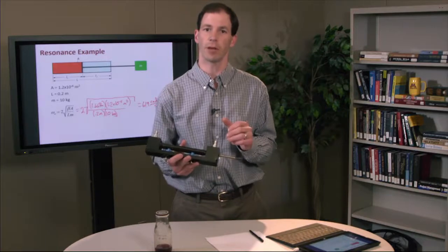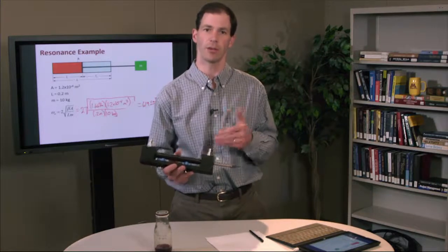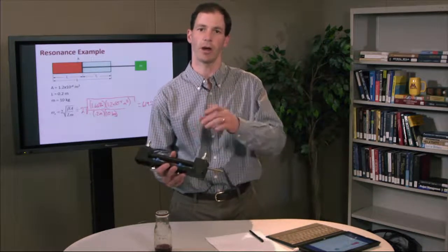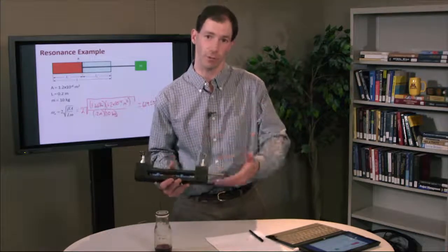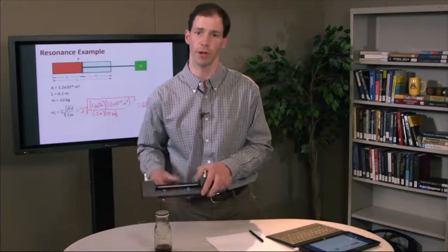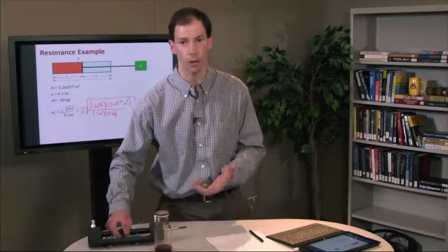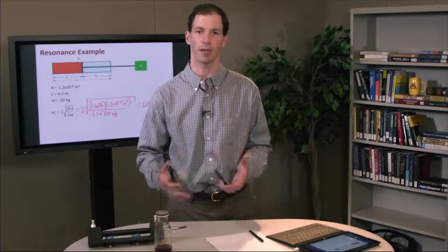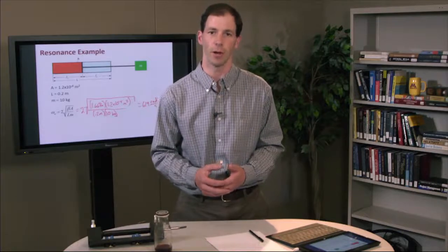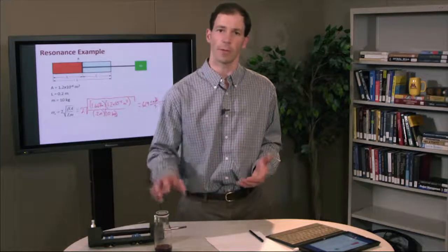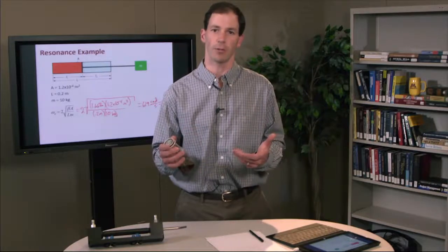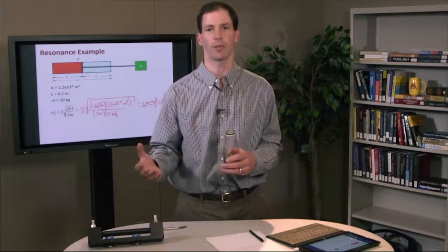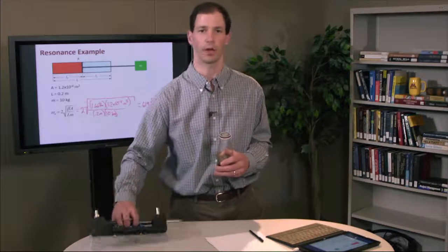One thing that I have neglected with this calculation is the additional hydraulic oil that would be between the valve and the cylinder itself. So there would be additional compressibility, which would further lower this natural frequency. So in some situations, a long, slender cylinder like this, we can have fairly low natural frequencies. So in this video, we've talked about the compressibility of hydraulic oils and how we model that with the bulk modulus equation, and then talked about a few specific cases where it's important, including this case of resonance.